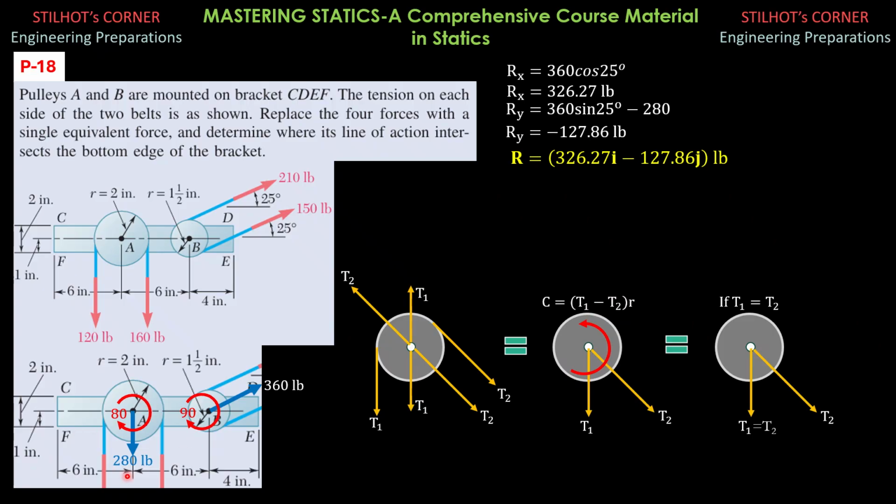You can make it positive if you want, but in this case, let's stick to the sign convention that counterclockwise is positive. So for the 360 pounds, we have two components, horizontal and vertical. The vertical component is counterclockwise, so let's treat that as positive. Moment about F is 360 sine 25 degrees times the distance, which is 12. So the vertical component produces a counterclockwise moment about F, and it is 360 sine 25, and the moment arm is 6 plus 6, so 12.